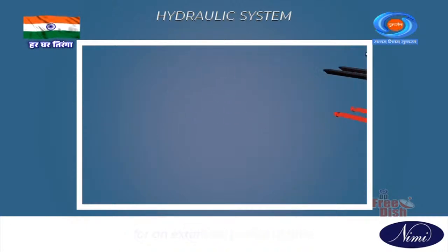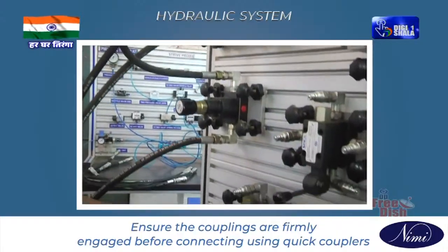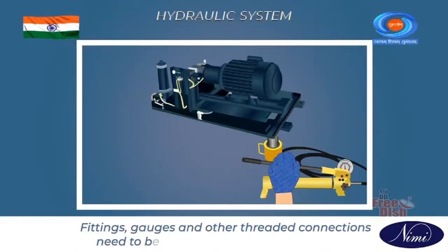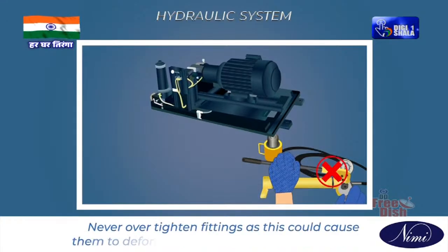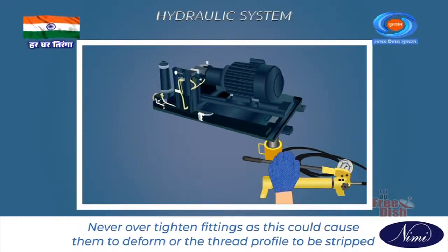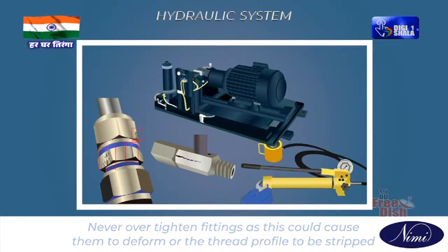Ensure the couplings are firmly engaged before connecting using quick couplers. Fittings, gauges, and other threaded connections need to be tightly screwed on and leak-free. Never over-tighten fittings as this could cause them to deform or the thread profile to be stripped.